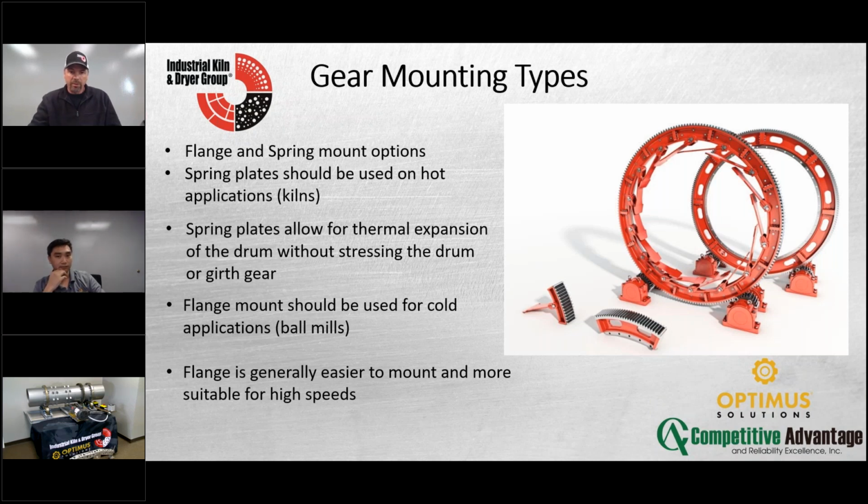Well, on this particular one that we're showing here on the slide, that tends to be more of a newer technology where you're seeing the multi-pieces like that. Yeah, the segmented gear. I would say one of the criticisms that segmented gears have had, say 20 or 30 years ago, is the precision, or how good of a quality control. If I have 100 pieces of this, are they all exactly the same, or whatever we define it as exactly, right? Is it within 5 thousandths on everything?